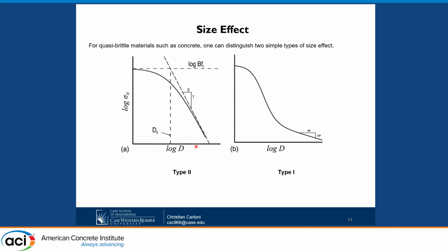Why do you see 2 graphs? The one on the left is the one we care most about for some applications, which is anytime you have a crack that will propagate until you fail the structure. The one on the right is when your crack will start propagating immediately and there will be no stable propagation. The one on the left is concrete notched beams, compression of cylinders. The one on the right will be your modulus of rupture. So they go down almost the same way, except that one will continue to go down and the other at some point will slow down a little bit on the slope. But I can guarantee you that all structures will have size effect if they are made of concrete.